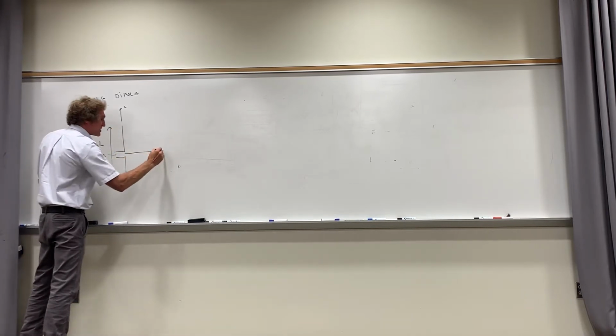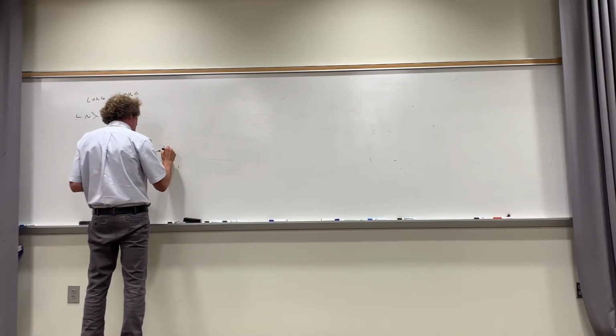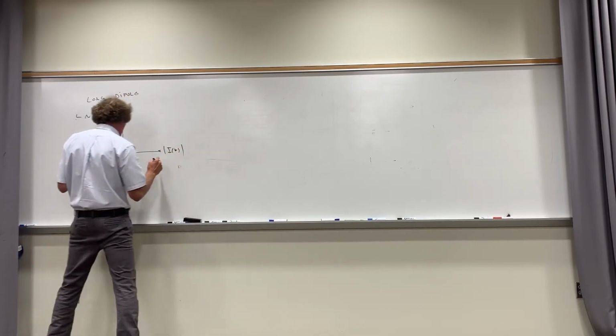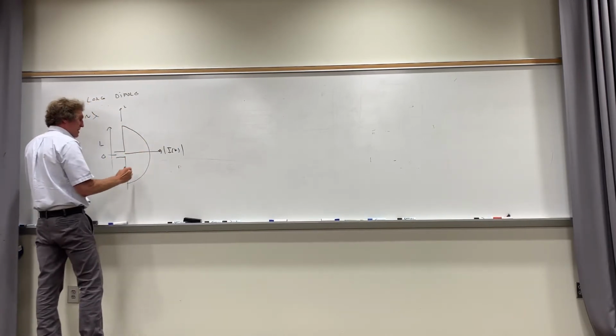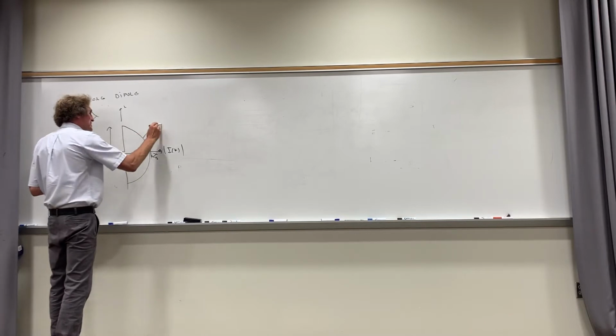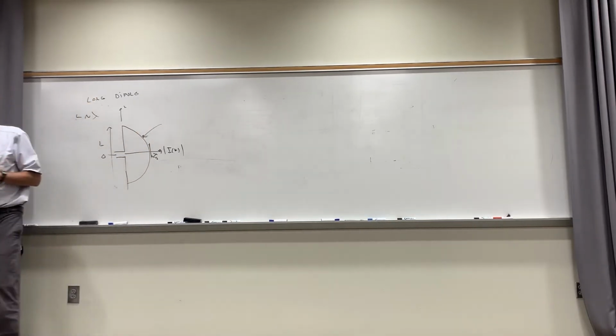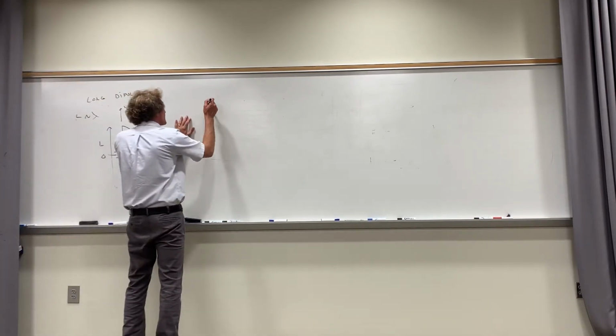If I was to plot the magnitude of I of z here on this axis versus this height, I would get this. It hits a peak right here, and that would be I naught. And the solution for this current is not a closed form solution. The way they actually solve this is they solve the Helmholtz equation, the del squared A operator, set things to the boundaries, and they literally solve for this current, but I'm not gonna do that. I'm just gonna say that's what the current is, write this down.